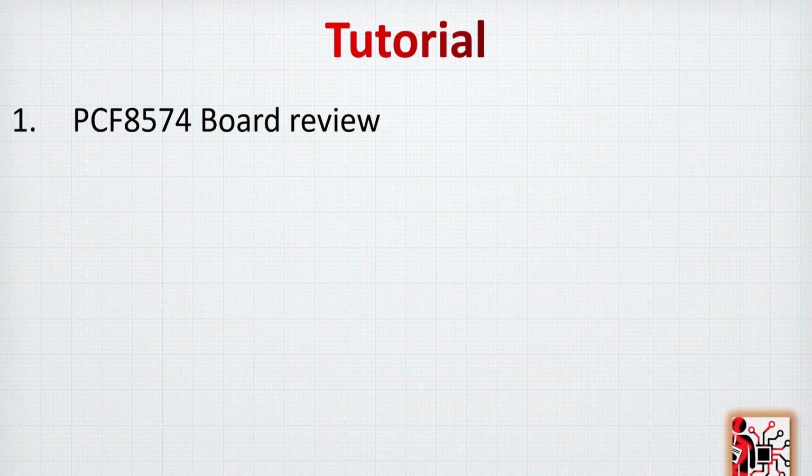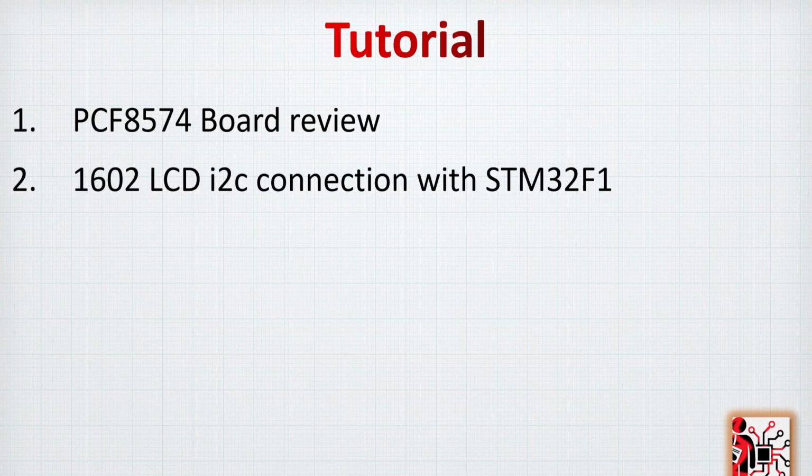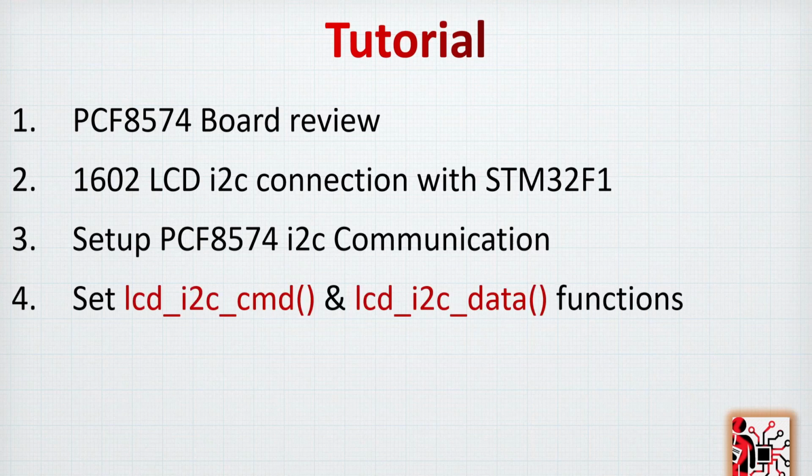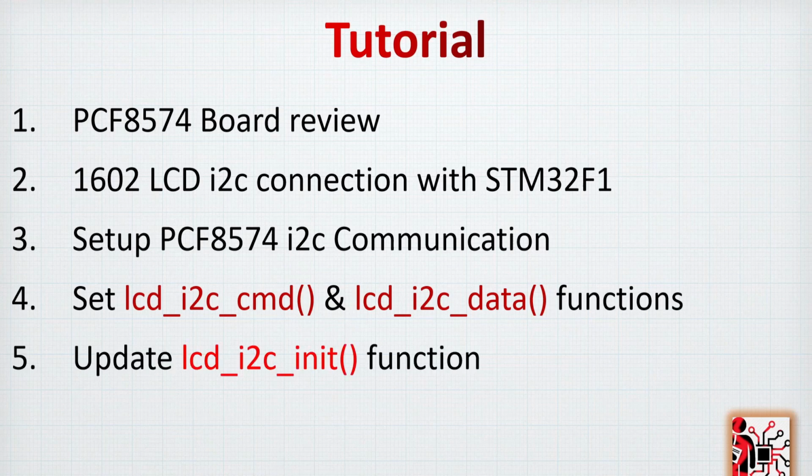So for the tutorial, first of all, we are going to take a very quick look at the PCF8574 board to understand how it works. Then we are going to understand the 1602 LCD connection with the STM and also with the board itself. After that, we are going to start coding, where we are going to establish the I2C communication with the PCF8574. Then we are going to update the functions that we used for control and data with the 1602. After that, we are going to update the initialization functions. Then finally, we are going to make some tests and display.